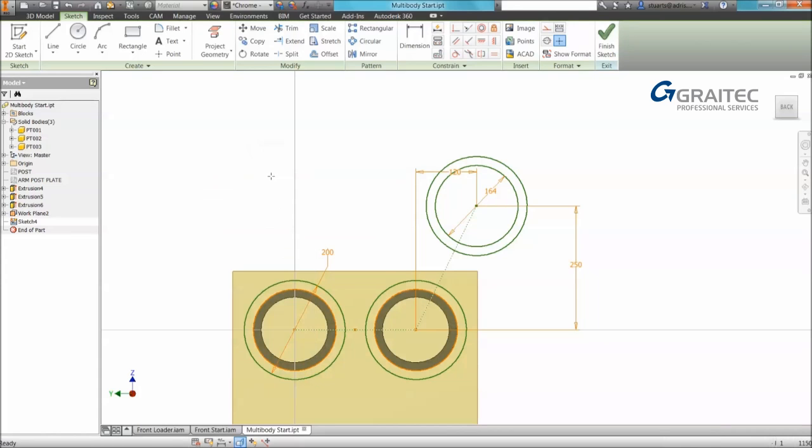So I also want to create some additional lines. Remember that if you hold the shift command, you can enforce tangency, which means I can create tangency at 2 points without having to apply a constraint afterwards. But remember, we can always apply a constraint afterwards by using the control right click command if we need to.